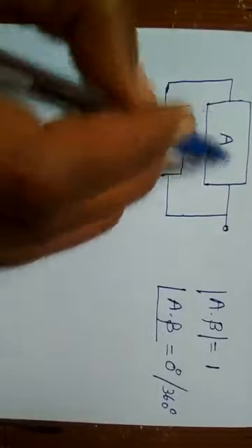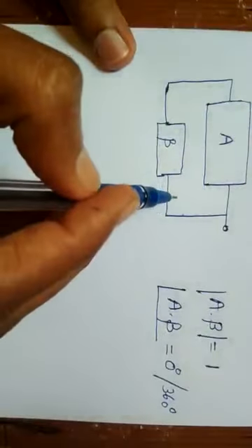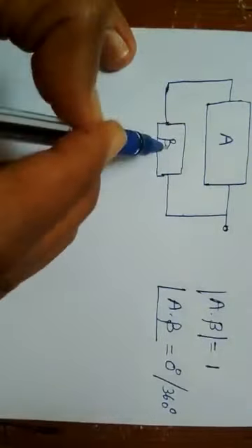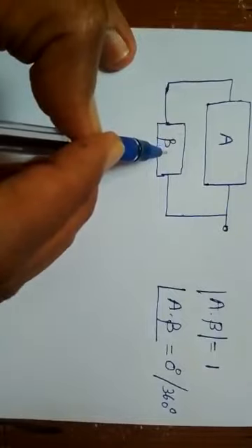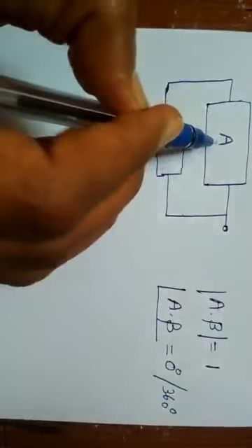By properly choosing the components, you can control the sustained oscillation into controlled oscillation, then this amplifier becomes an oscillator. Repeat, if this amplifier with forward path gain A and feedback path gain beta satisfies Barkhausen criterion, the name is Barkhausen criteria,